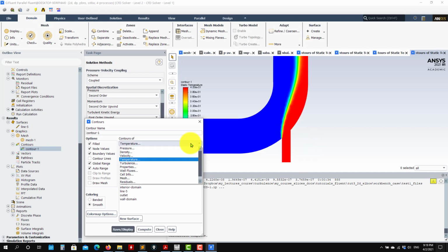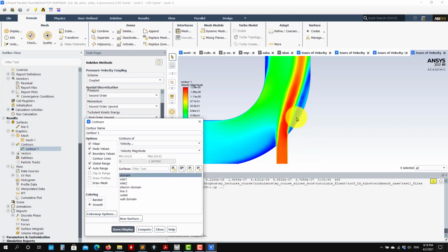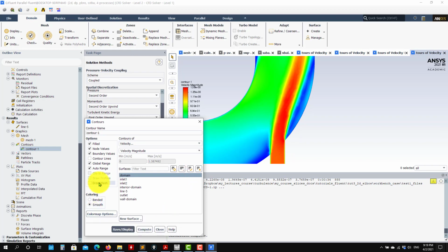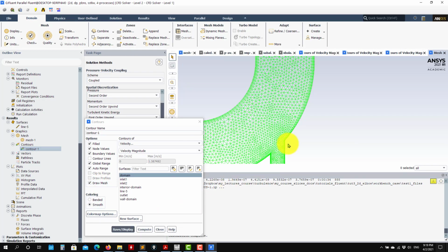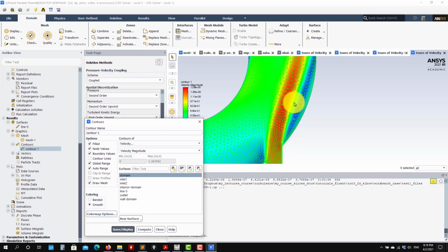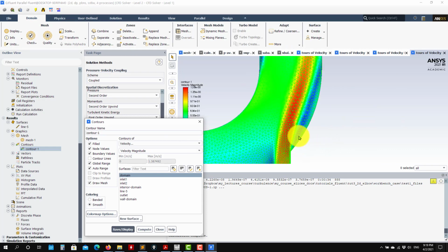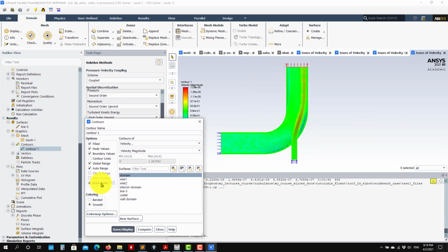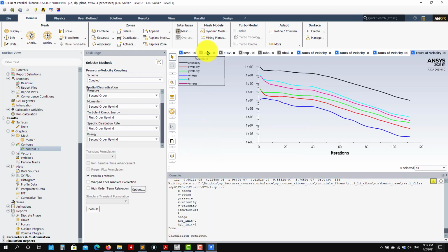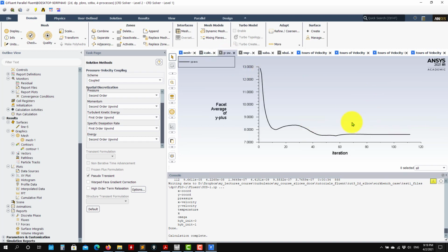So see here that velocity, and see here that even the mesh it's not perfect, it's not super fine, but it's interesting to see that here it managed to capture here there is a recirculation, and here also. Okay, so this is the turbulence model. So now if you try to run this case laminar, you will see that you will get very different behaviors. Likely the case won't converge. Okay, this one will remain stalled. There will be a lot of oscillations there. Okay, so try to do it in laminar.